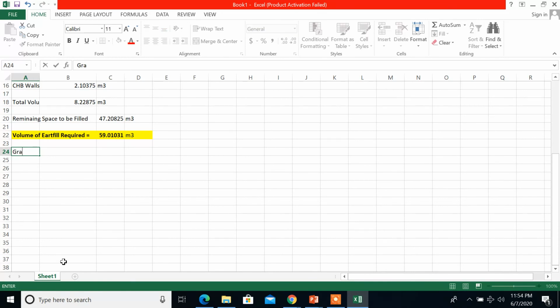Then next, since we're done with the earth fill, punta naman tayo sa gravel fill for concrete slabs. Usually, a concrete slab on fill is poured on a layer of gravel or any other approved coarse aggregate, to provide a firm foundation. This gravel base, where so indicated in the plans or specifications, should not be overlooked when estimating the materials for concrete slabs on fill. Its volume is equal to the area of the concrete slab multiplied by the specific thickness of the gravel.